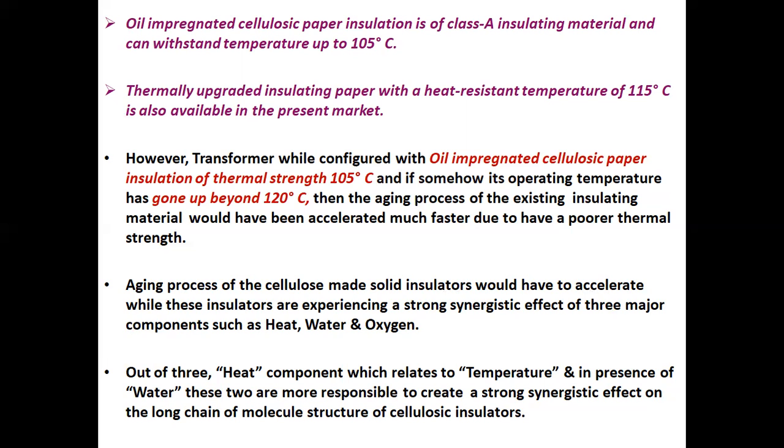Out of three, heat component which relates to temperature, and water, these two are more responsible to create a strong synergistic effect on the long chain of molecule structure of cellulosic insulators.